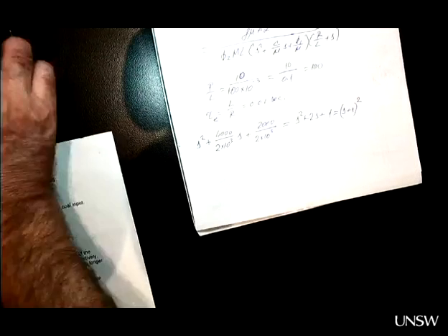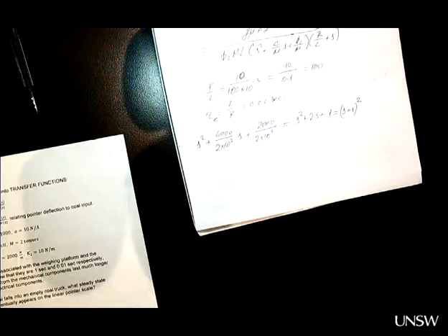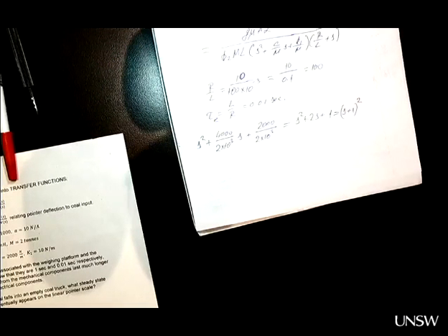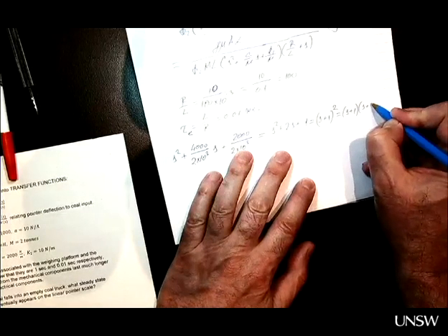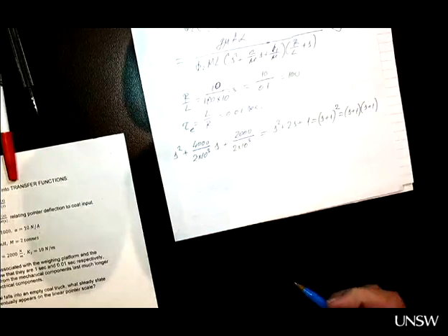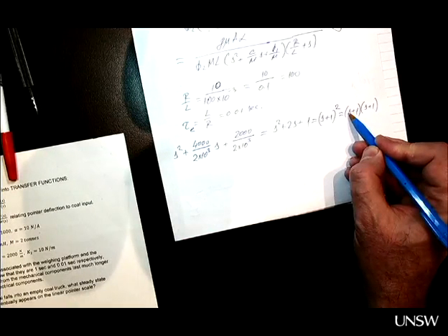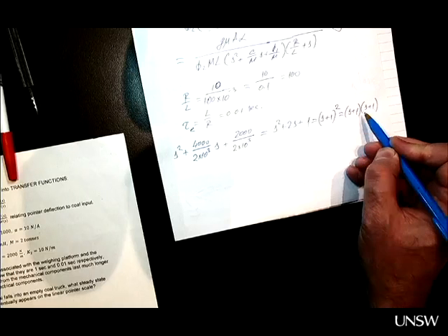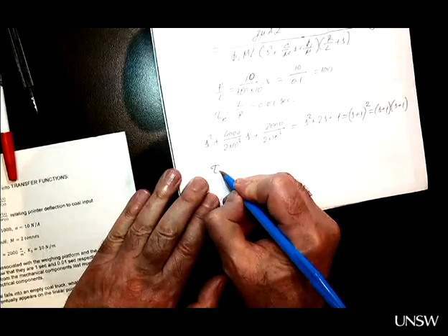At this point, our life becomes much easier because although we have 2 time constants, they are the same. They are the same because, do I really have to write this? This is equal to S plus 1, S plus 1. So we have 2 time constants. This is 1, this is 1. So what multiplies S is the time constant. What multiplies S here is the time constant. So you have 2 time constants, but they are the same, and they are equal to 1 second. So this is mechanical part. Tau mechanical is 1 second.